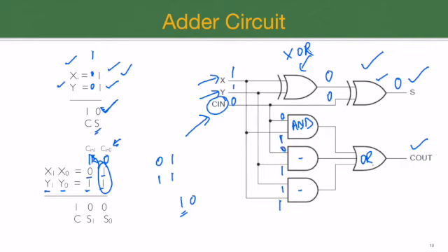and that's it. Okay, so 0 and 1 will produce a result of 0. 0 and 1 will produce a result of 0. 1 and 1 will produce a result of 1. And all of these three values are being ORed to produce the C out output. So OR operation, if any one of these values is 1, we will get the result of 1. So we can see that this value is 1, therefore a value of 1 will be produced over here. So our result will become C equals 1 and S equals 0, which is what we can see over here.